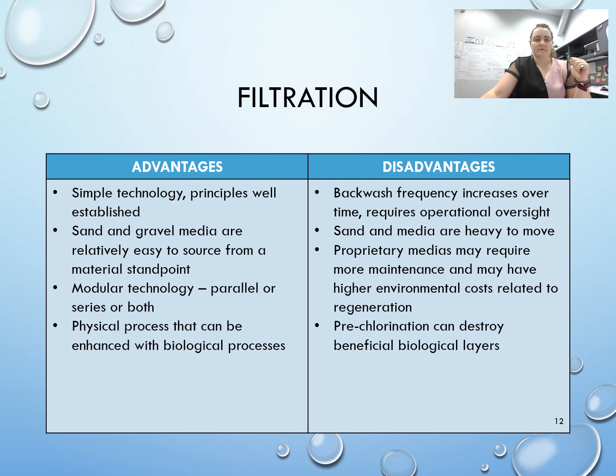So advantages: it's a relatively simple technology. The principles are well understood. Sand and gravel media are relatively easy to source from a material standpoint. They're not difficult to get. It's a modular technology, so we can put things in parallel, we can put things in series, or a combination of both, and it's going to work really well.